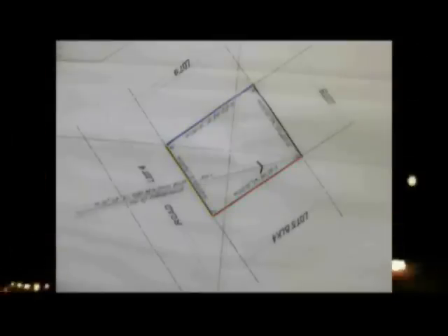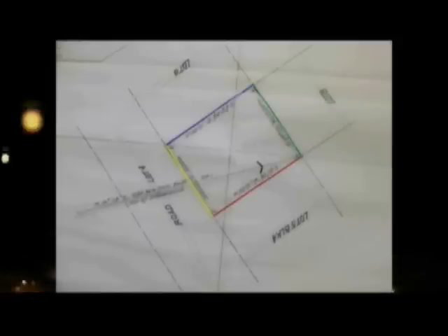South 90 degrees 28 minutes east, 3,740.34 meters from BLLM Parañaque. Then on north 40 degrees 4 minutes west, 15 meters to point 2. Then on north 49 degrees 56 minutes east, 12 meters to point 3. On south 42 degrees 4 minutes east, 15 meters to point 4. Then on south 49 degrees 56 minutes.